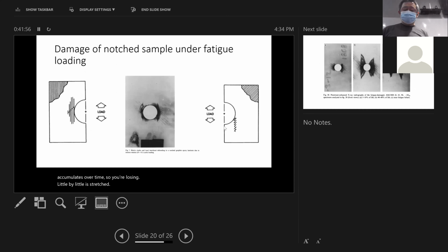Notches are commonly seen in composites. When people join composites together, frequently they use fasteners, right? You bolt one section of an airplane together with another section. So you drill holes in them, and you have to deal with the holes. When you have holes, you basically open up a can of worms. The hole is a stress concentration, and the stress concentration is also dependent on the layups.